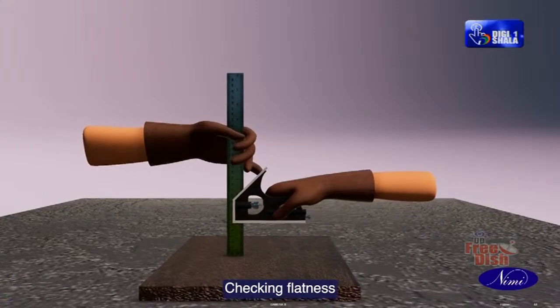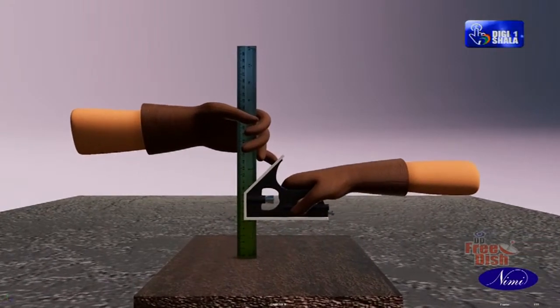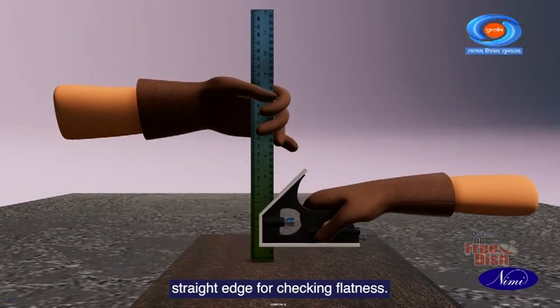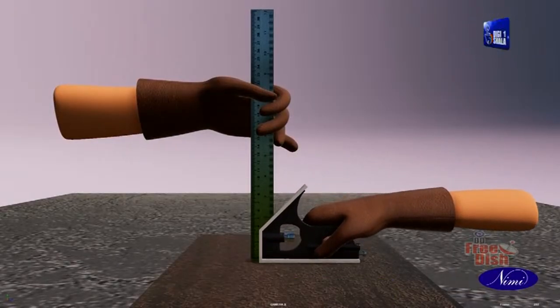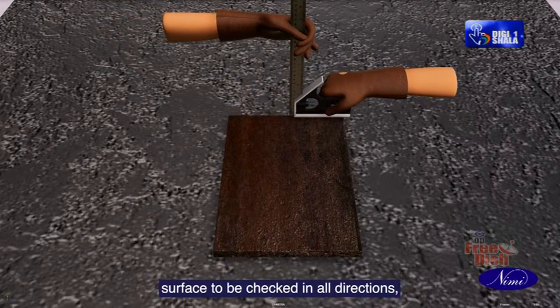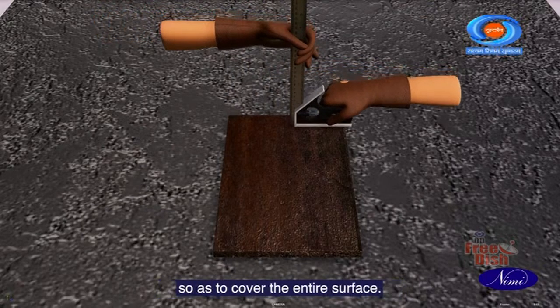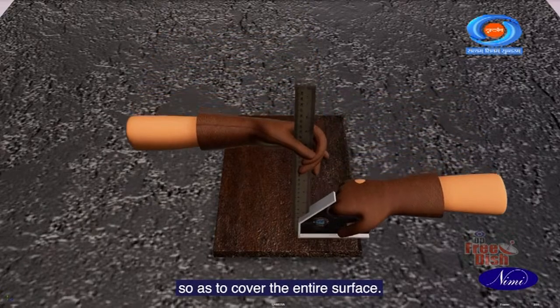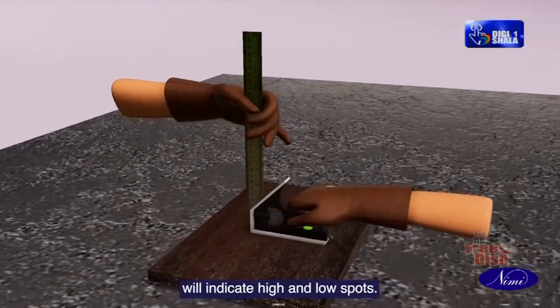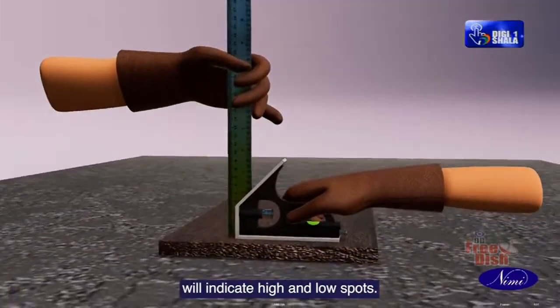Checking flatness. Use the blade of the tri-square as a straight edge for checking flatness. Place the blade of the tri-square on the surface to be checked in all directions so as to cover the entire surface. The light gap will indicate high and low spots.